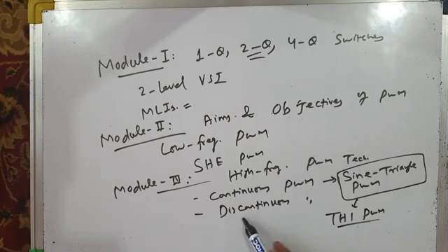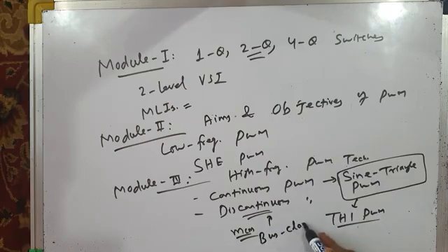And then we discussed various discontinuous PWM techniques, where we injected common mode signals, which were mostly triple frequency. These common mode signals, we added them to original sinusoidal modulating waves, and we got various types of discontinuous PWM techniques, which we also called bus clamping PWM techniques.